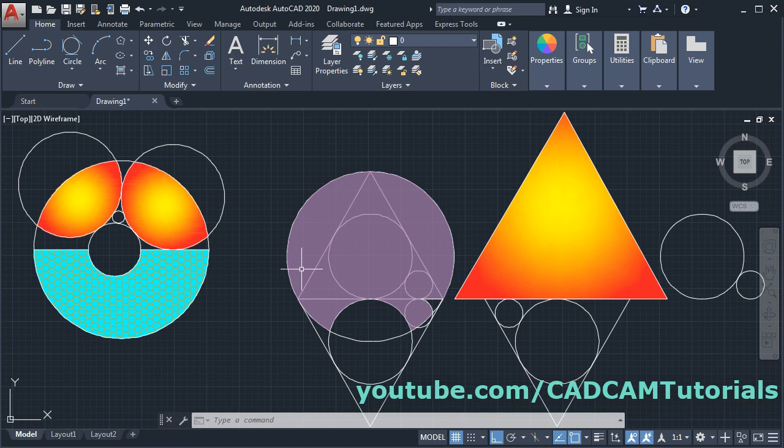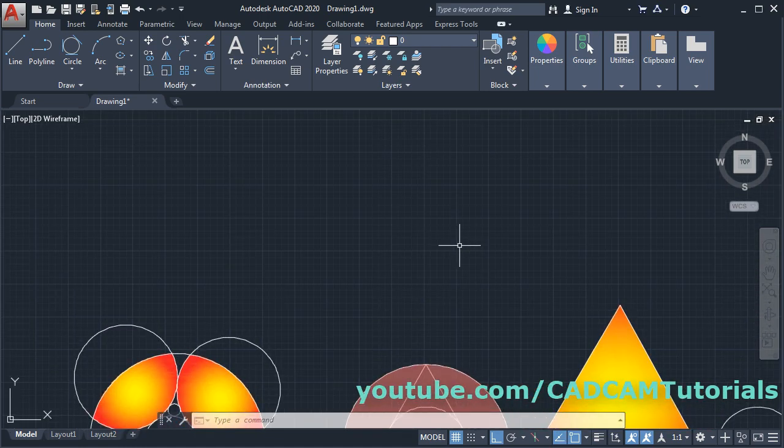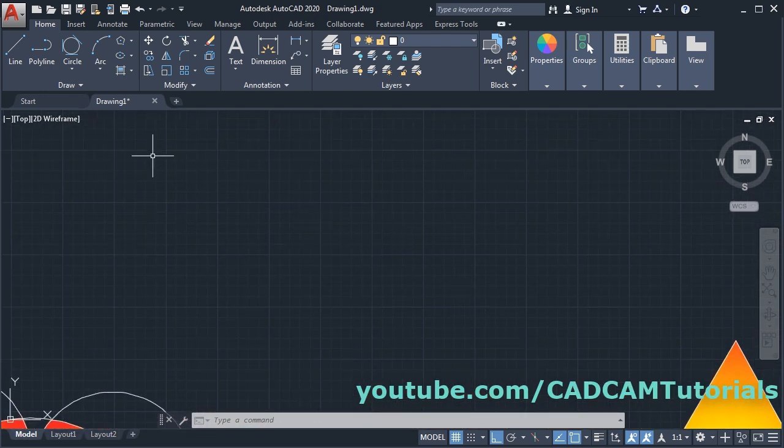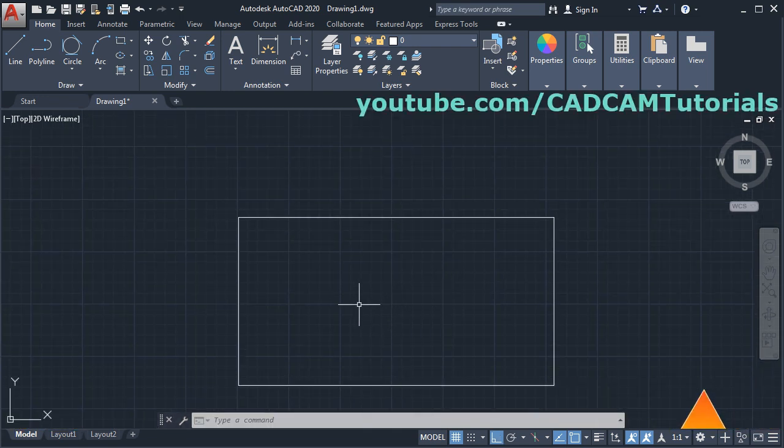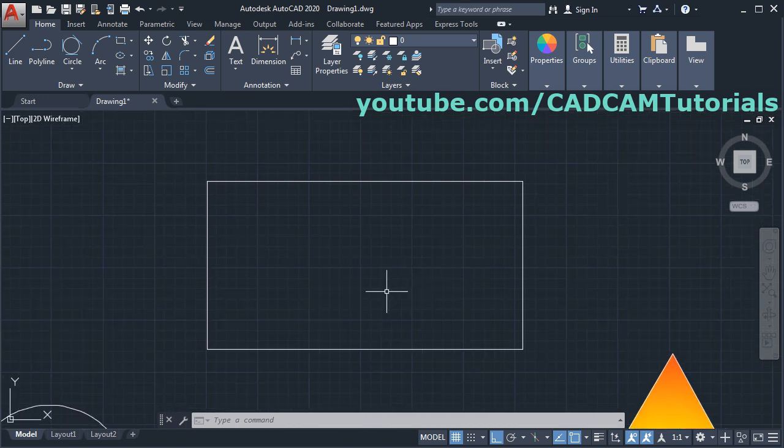Then next is object snap tracking. Now object snap tracking is useful to locate points with reference to other points. Suppose here I will create one rectangle. Now in this rectangle I want to create a circle at the center of this rectangle. Normally I have to create one line from the midpoint of this line to this line, and then at the midpoint of that line I have to create the circle. But using object snap tracking you can locate this center point without creating any reference objects.